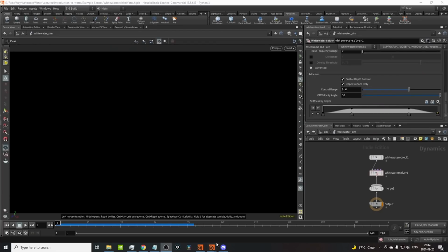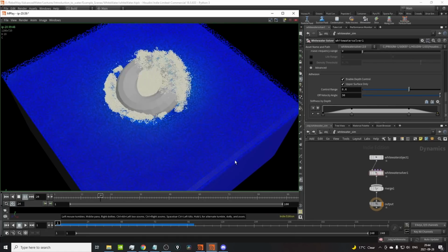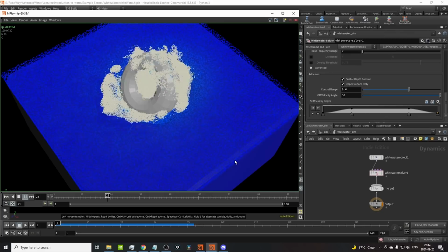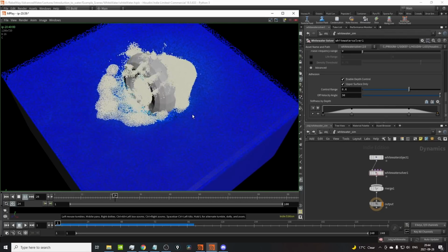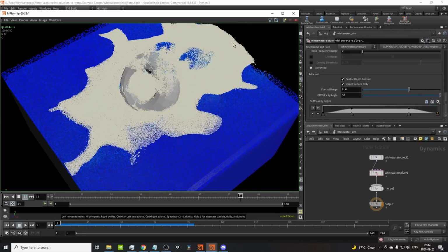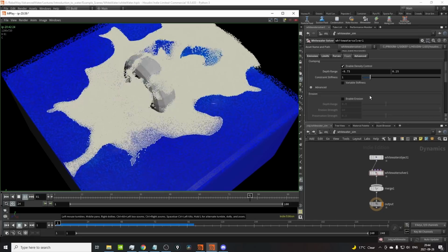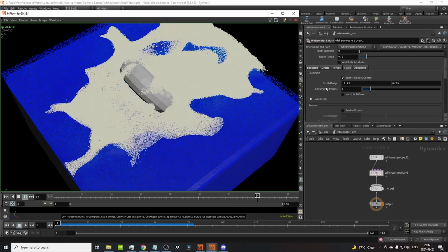Okay, so I ran a few of those simulations, and here's our default. This is what we're having without any shaping changes, what we had before I went off to simulate some things. The only thing I changed here from the version before is that I ran this through with the volume limits turned off so that our foam disappears. The first setting under the foam options is our clumping.